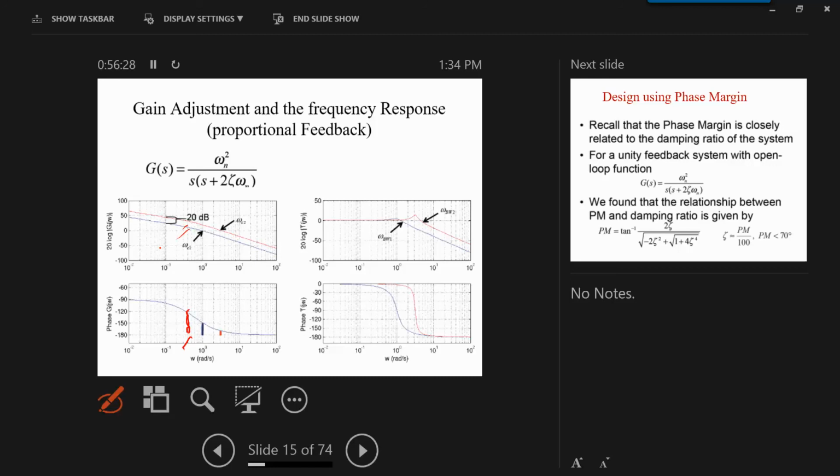Just like when we did here. Suppose my desired roots come from the damping; I got the damping of 60 degree. I draw the 60 degree line, and this is the intersection. At the gain I have, for example, the root locus is here. I want to increase the gain just to bring it to this point.